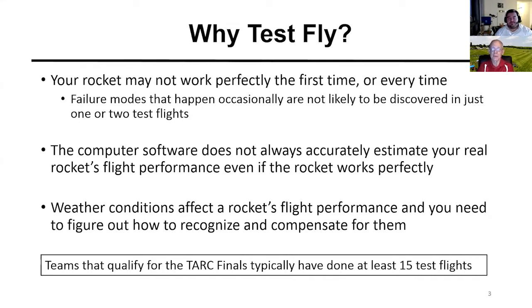And you need to build up enough experience and fly your rocket often enough that you find all those odd failure modes that otherwise will probably happen to you either in your qualification flight or when you get to the finals. So practice makes perfect. Perfect practice makes perfect. So the computer software is really good. It gets you in the ballpark, but it does not exactly give you the altitude and performance you're going to actually get with your real rocket. I'll talk about why.